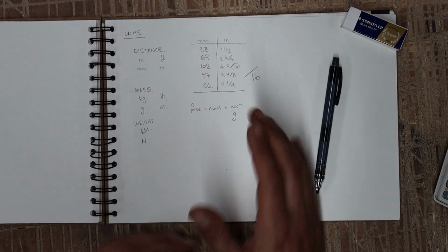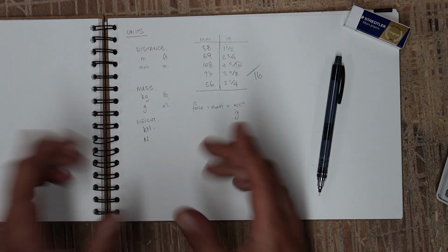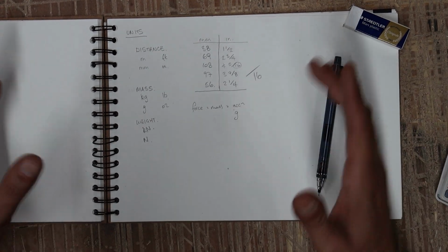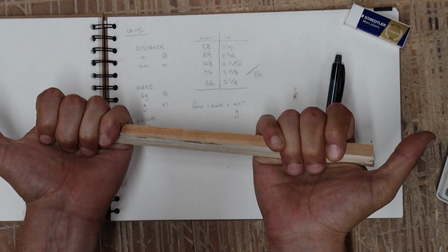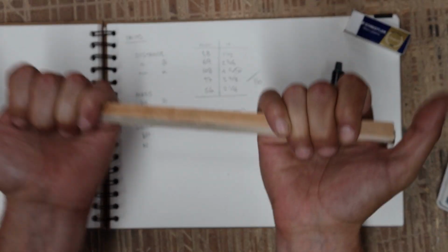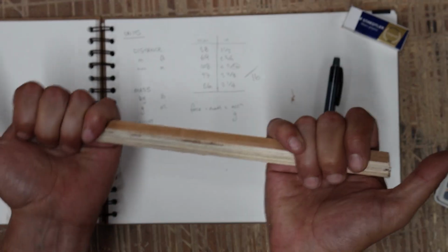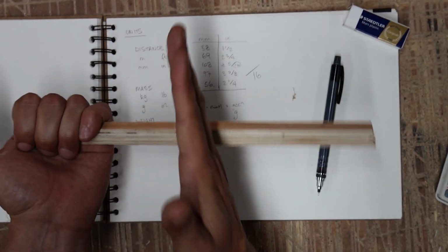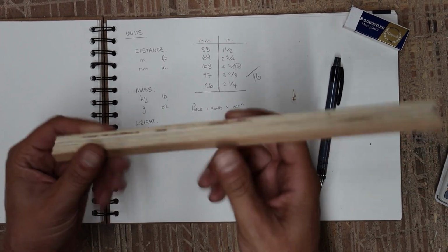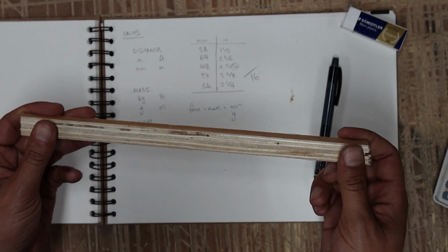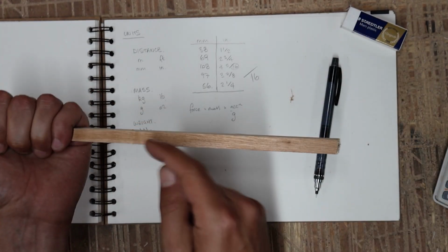Okay. Now, from a structural perspective, we tend to combine these into something which we call stress. Now, if we take a structural member, I've got a piece of wood here, and we apply a force onto the ends of it, so essentially putting this piece of timber into tension, then we define the stress by the force divided by the cross-sectional area of the member we're talking about. And we are assuming that we're going to get an even distribution of stress through the member, and that isn't necessarily the case. But from a stress perspective, that's how we calculate it. We divide the force by the cross-sectional area.